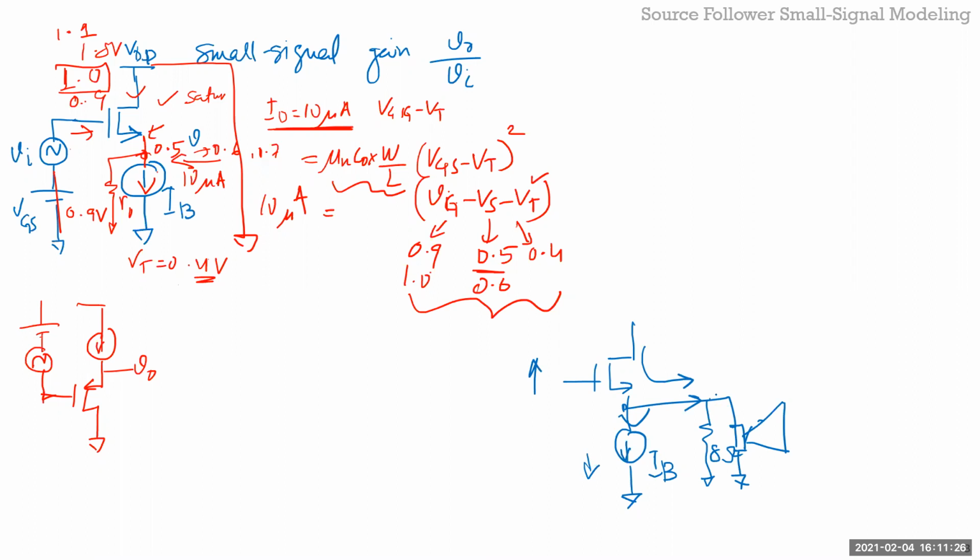Okay, so let's say this is 1 volt and it requires 100 milliamp, something, I mean, it's 8 ohms, so it should be 8 amps. But let's say, change this. So let's say 800 millivolts divided by 8, so that'll be 800 milliamps. So you need 800 milliamp over here. So obviously, if you bias it with 10 microamp, it's not going to cut it, right? So you need to bias this at least with like 1 amp.